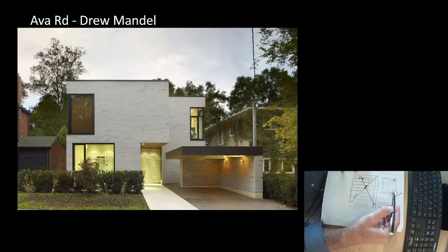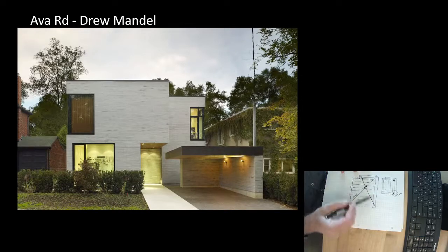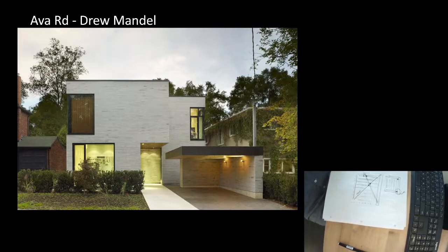The other thing is that this element sticking way out here, picking up all that load, would tend to sag a lot. What this does is gets the load straight to its point of resistance in the most direct way. So when we're dealing with big two-way cantilevers, very often a diagonal beam is the way to make things the stiffest.